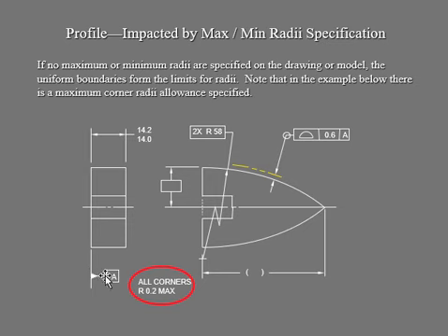Datum plane A can be seen only on the right side, based on this example. Of course, we have the size shown from here to here, you can vary between 14.0 to 14.2 in that zone. And I have, of course, a 2.